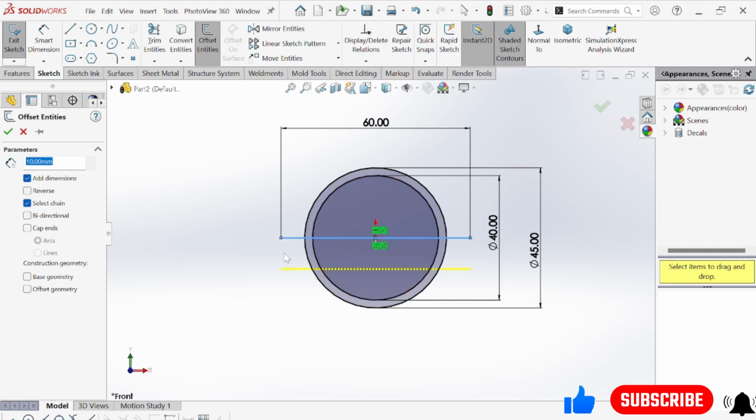And again go to offset, select this one because we need to offset this one. We need one more line, but we are not going to make this one manually. We will offset this one and make it 2.5 mm. Make this one reverse because we also need thickness, and the thickness of this one will be around 5 mm. This one is already 5 mm and this one is 2.5. Let me check if it's 2.5 or not.